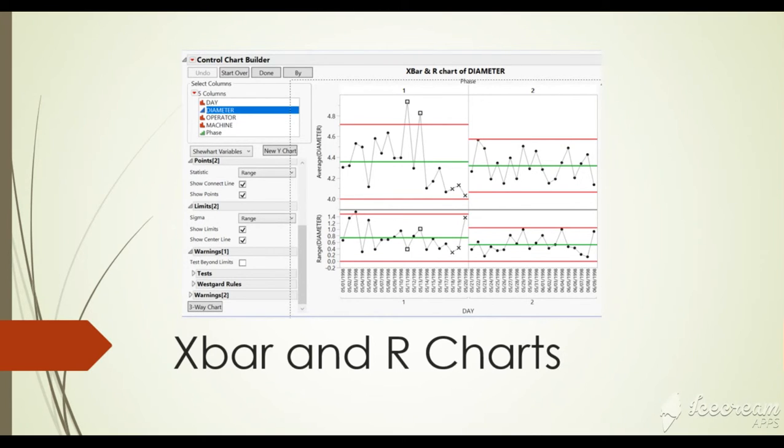And looking at both charts, there are some sudden moves and two plots that are out of control, but the overall plots are all within the lower and upper control limits, and the overall plots are decreasing, which means the process of the product is showing constancy in making their product.